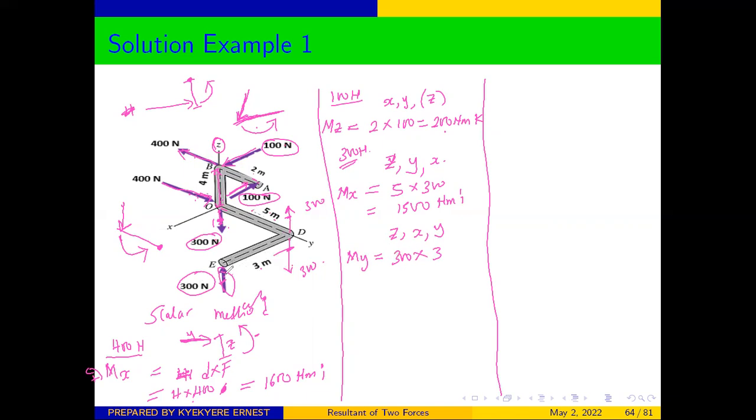If we apply a force down here, with this side fixed, you realize that the rotation is going to be in this direction, which is clockwise. Therefore, our answer is going to be negative 900 Newton meter, and we said that the rotation will be in the y, so j.